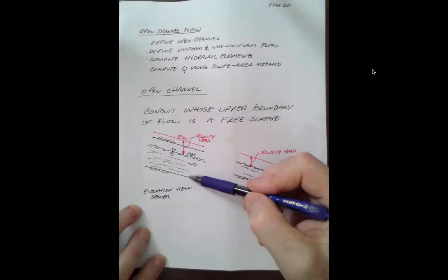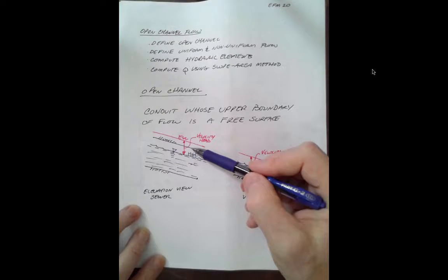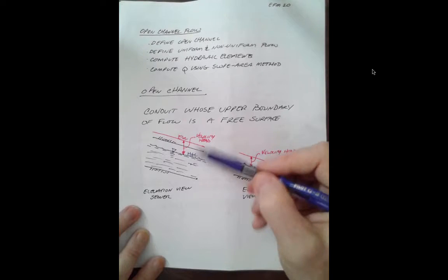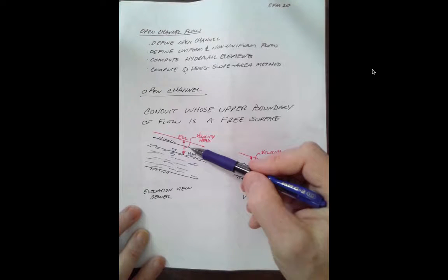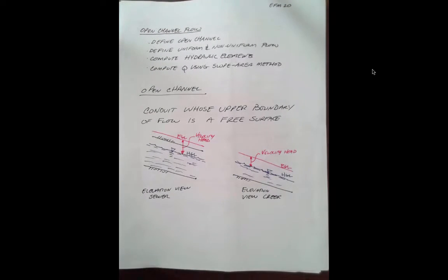If the liquid in the sewer gets up to the top, then it becomes a pipe under pressure, and if there's any additional pressure added, then the hydraulic grade line comes up to the top, and then it keeps going up, and that's a pipe under pressure, and that was discussed in prior part of the class. Okay, examples of open channels are creeks, ditches, rivers, canals, and sewer pipes that are partially full.